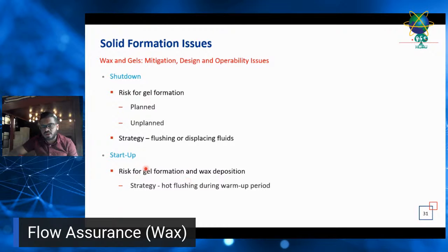Or we can also heat the flow line first, before starting up your well. So that's one more strategy that can be employed in this startup scenario. We can heat up the flow line above our pour point or above WAT, and we can actually compute the duration of heating using software. After that duration of heating, we can start flowing the wells.